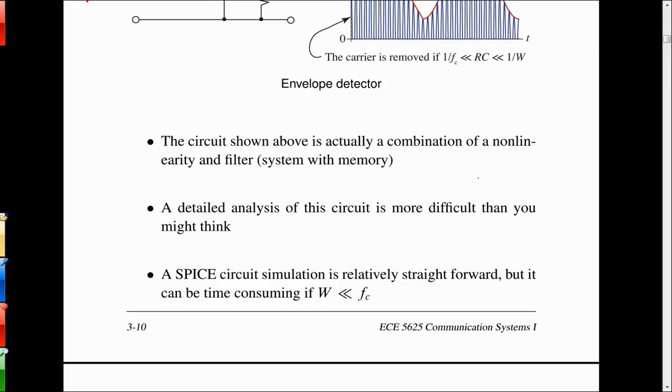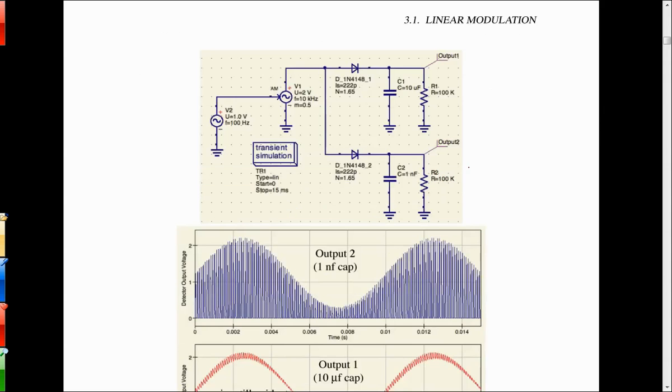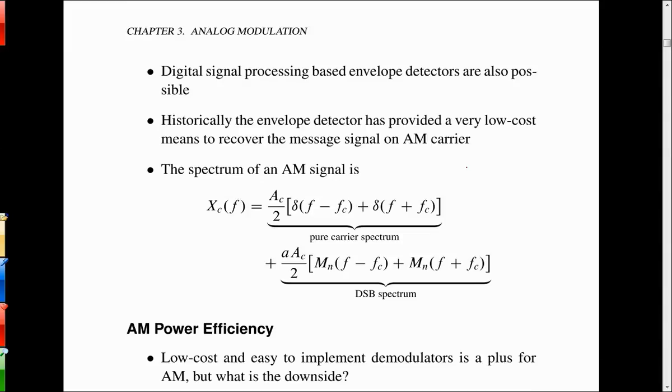It's just something that you will only be confronted with when you are in a position where the job says you've got to figure out how to make an AGC amplifier work. It has an attack time and a decay time, which takes me back to the radio broadcaster. I can picture listening to a baseball game where they pause and the gain rises up rather slowly. Then as soon as he starts talking, it instantly re-regulates. So it has an asymmetrical time constant on the gain control.